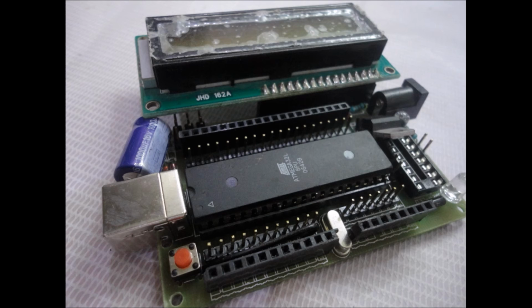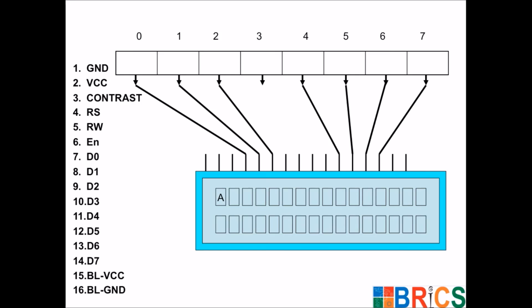Now this is the bootloader board which we use. In this board you will find one ATmega16 and one USB connector through which we transfer code. On this board you will find a small 16-pin connector near port C. If we plug the display on this port, port C of the ATmega16 or 32 will get connected as per this diagram.